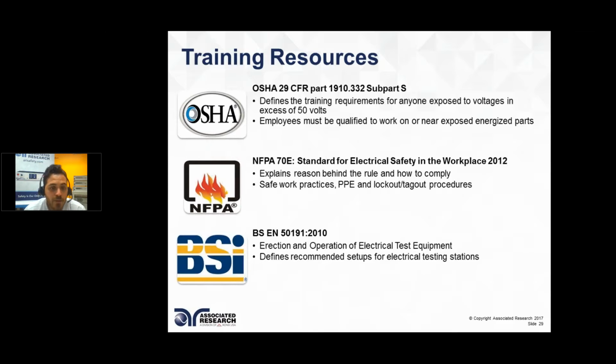But till then, feel free after this webinar is completed to go on our website and look for training resources, or just review the OSHA regulations on what they feel is mandatory to provide safe workstations for anything that exceeds 50 volts. And also, it dictates that employees must be qualified to work on or near exposed energized parts.